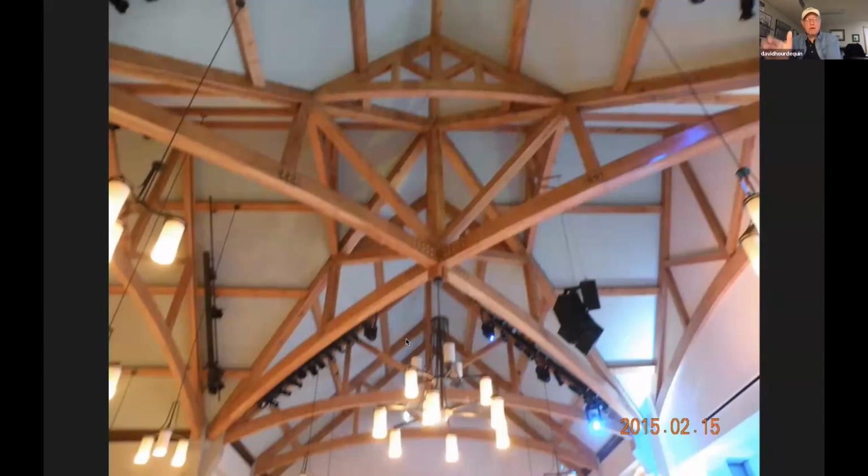Interesting thing as I talk about that, about wind loads, is that the allowable stresses under wind load in any load combination, including wind, can be increased by 60%. So seldom, I'm not saying always, but seldom does it control the design, except for maybe top chord truss stress reversal in super high wind loads. You get into 160, 170 mile an hour wind zones.